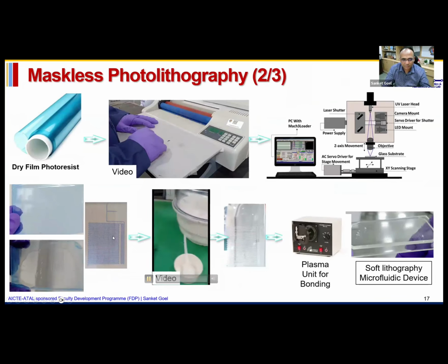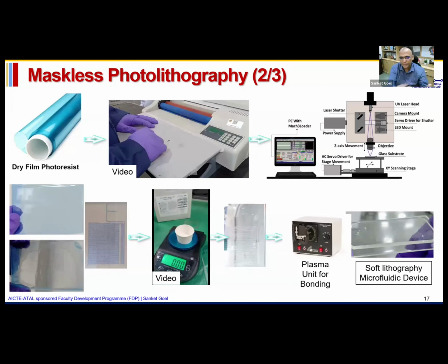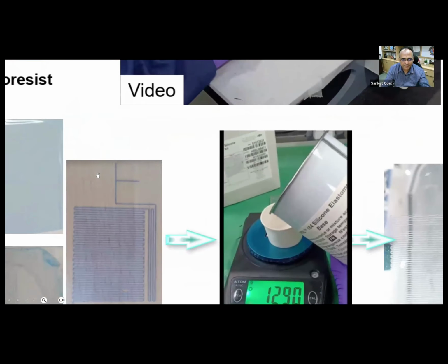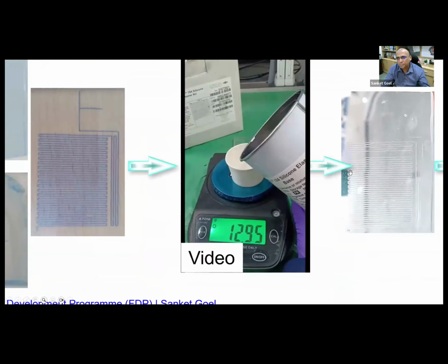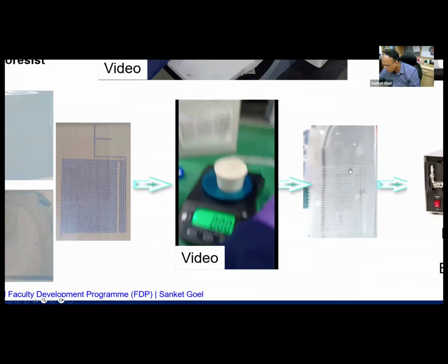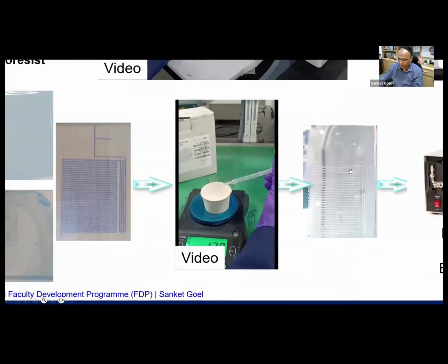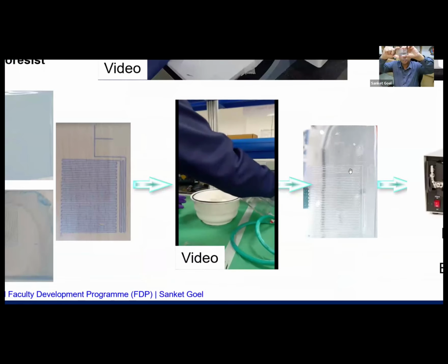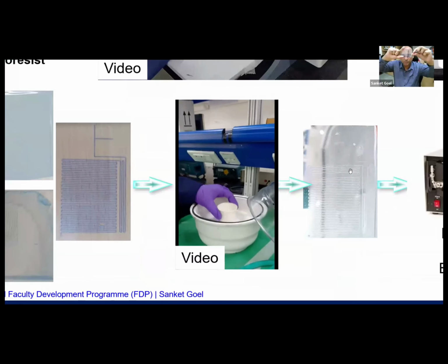So what it does is that we pour a layer of PDMS on top of this substrate, and after baking it, we peel it off. Whatever you see here on my left side can be reproduced on the polymeric devices. One example I have is this device. This is a kind of PDMS polymer. It's so flexible. I'm just showing it to you.